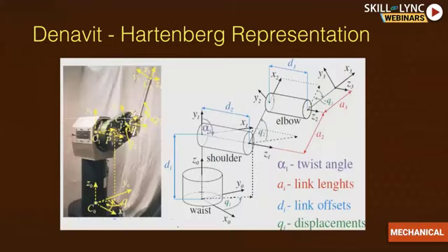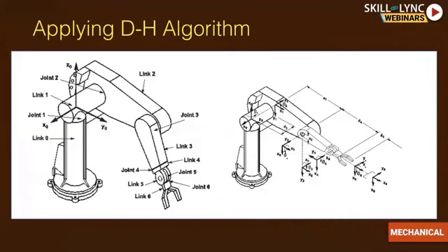And this is the very famous Denavit-Hartenberg representation. It helps us convert the robot which you see on the left to the robot which you see on the right. That is, both are the same. But if you look in depth, this is nothing but a geometric representation. The left is the diagram which we just saw in the previous slides. So I can convert any robot into a geometric representation, and this helps me mathematically create my arm equation. The creation of the arm equation is called forward kinematics. Now solving the arm equation to find the thetas, that's going to be our inverse kinematics.